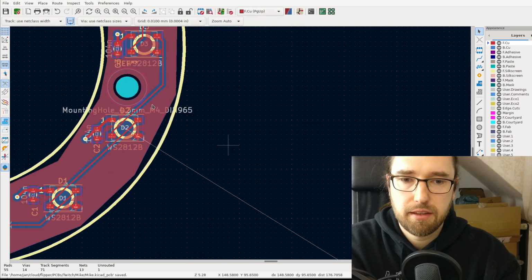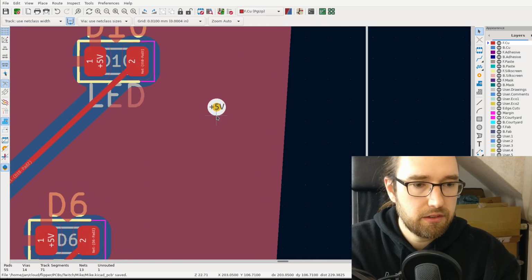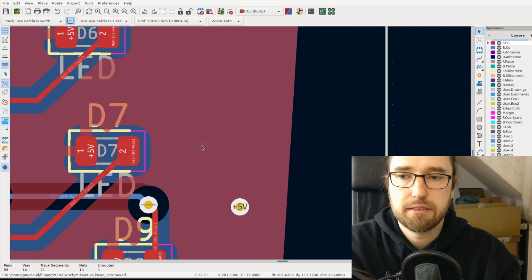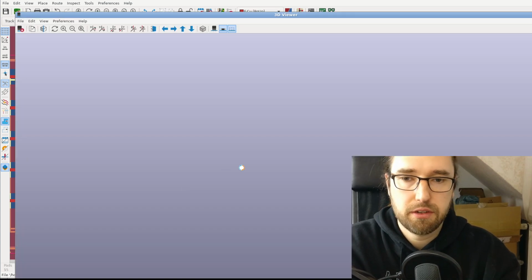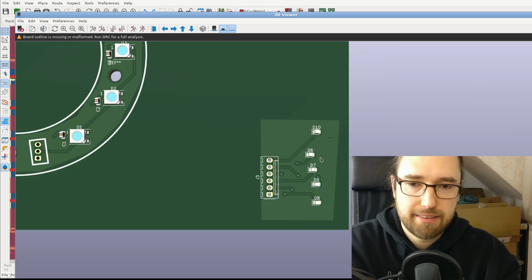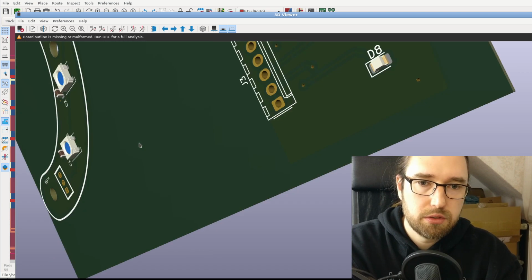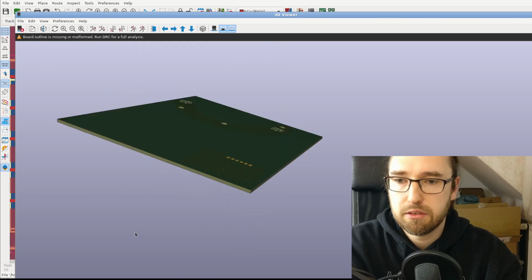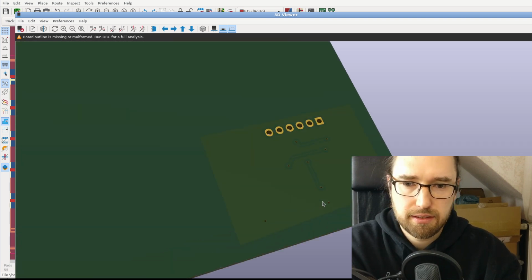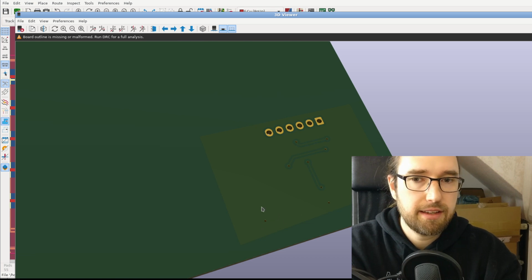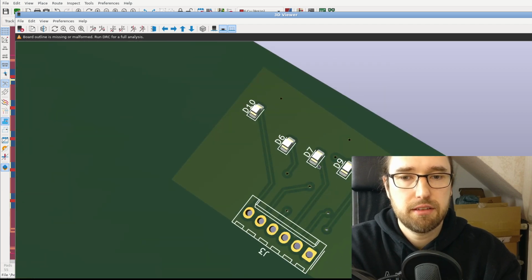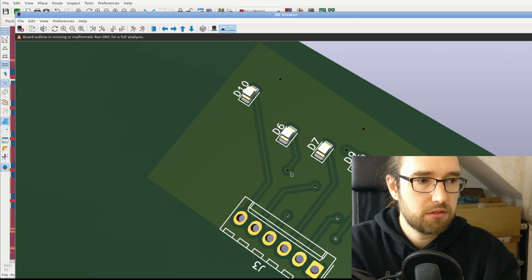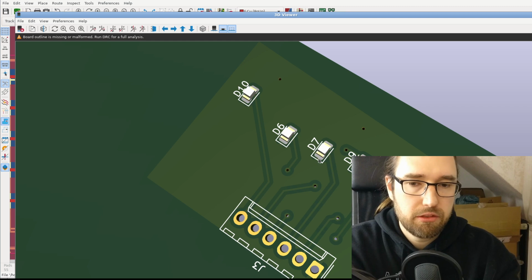But what you can see now is that we connected those 2 layers. And that's also then... Usually I would do it next to the parts I want to cool. So yeah, the outline is messed up now. But you can see those small holes here, and they go through and connect the 2 layers here. So here you can see the other side, and it just connects those 2 planes. And that's also good for cooling. So if you got a plane on the other side, it makes sense to allow the heat to dissipate via those wires to the other plane for cooling reasons.